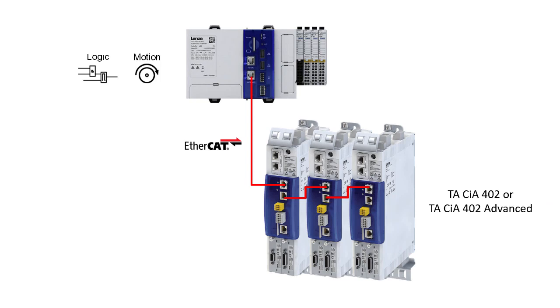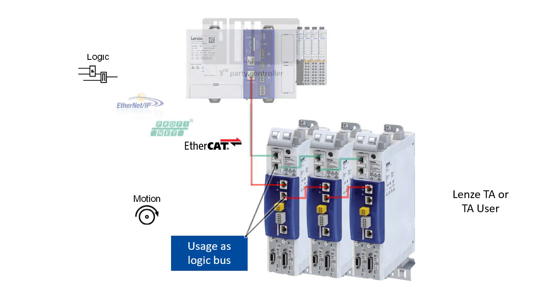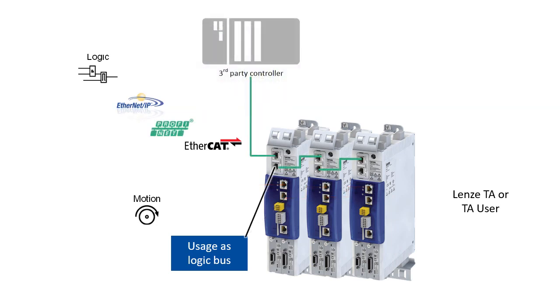In the decentralized topologies, where central logic is inside the PLC and motion functionality is inside the drives, we could use either EtherCAT onboard or Fieldbus EtherCAT, Profinet or Ethernet IP modules at the drive. If synchronized motion control is to be set up between several drives in the decentralized topology, the logic communication to the master controller must be done via the Fieldbus modules.